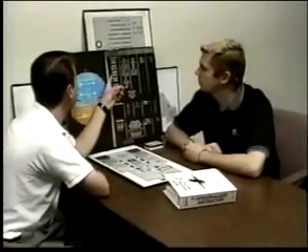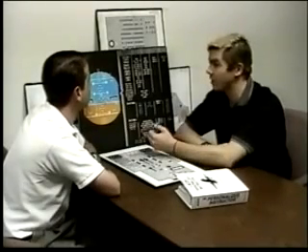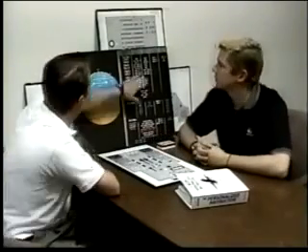Let's say you forgot to set that flex temperature or that assumed temperature into the MCDU. You get the throttles to the flex detent. Would anything occur? Yeah, after about a second or two, I'm going to hear a single ding, and then there's going to be an FMA up there that says flex temp not set. Appropriate response would be to shove both throttles up to the toga detent. However, if I didn't recognize that and I was wondering what was going on, I pulled the thrust levers back to idle, I'd want to continue with the abort, even once I realized it, because we don't know the performance at the point that we're at on the runway.